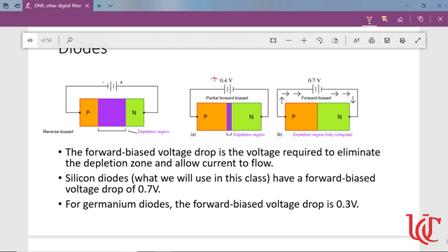The longer wire always means positive compared to negative, and if I apply positive to this P, then the depletion region I had will start to decrease. If I apply even higher voltage, from 0.4 to 0.7 volts, I might get that depletion region to go away entirely. And now I get current to flow. If I apply them in the wrong direction, though, positive charge to N, negative charge to P, my depletion region just gets even larger, in which case I don't get current to flow.